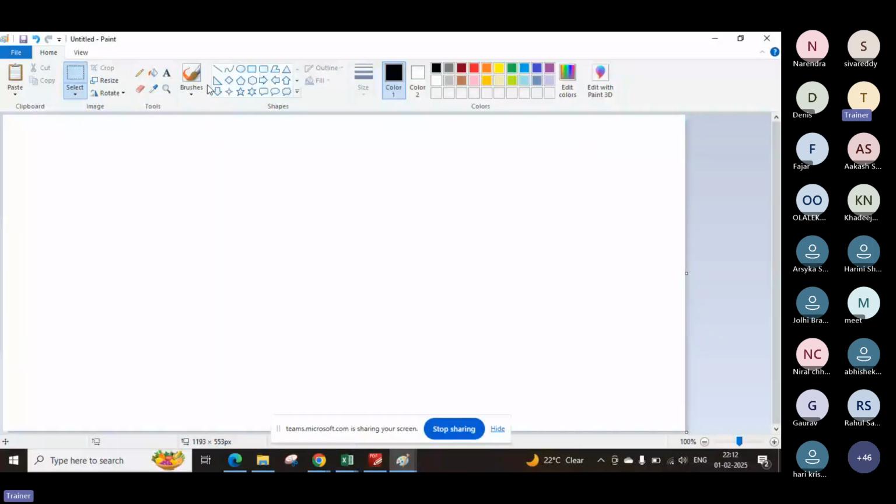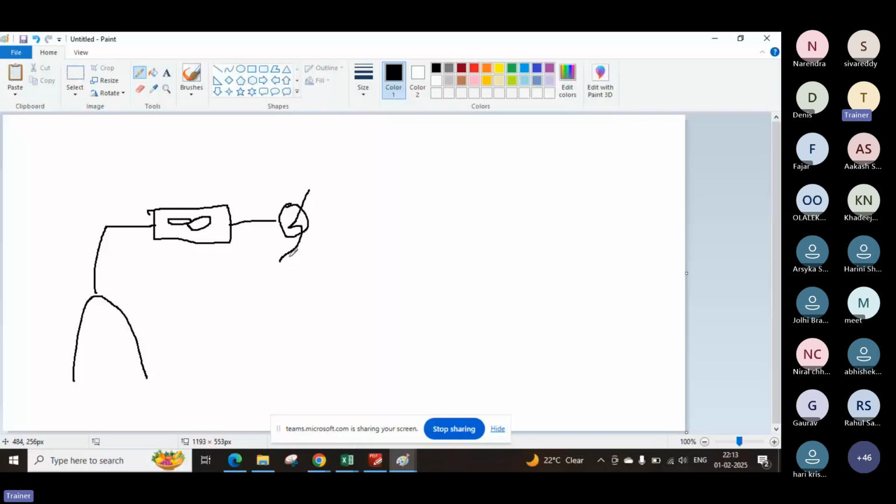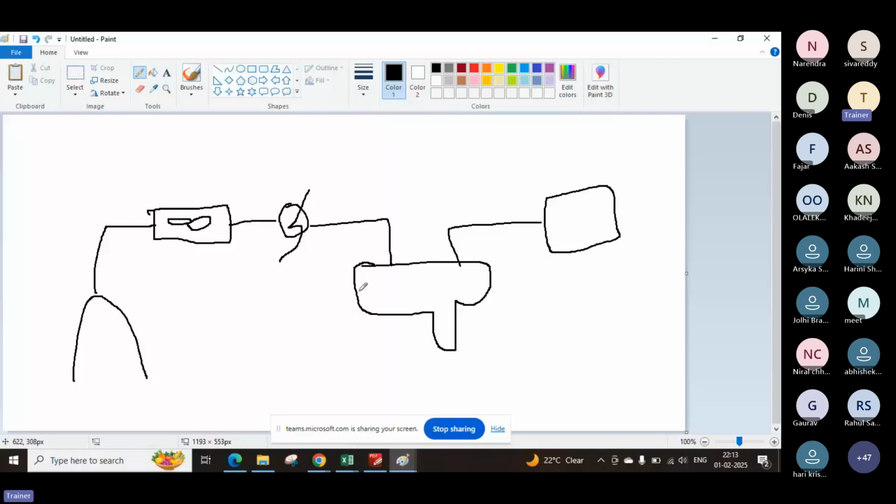Okay, suppose this is the distillation column, there is an air cooler followed by a water cooler, then you are having a separator, and this is connected to your vacuum system. Okay, so generally based on the liquid or the applications, this is generally horizontal only.